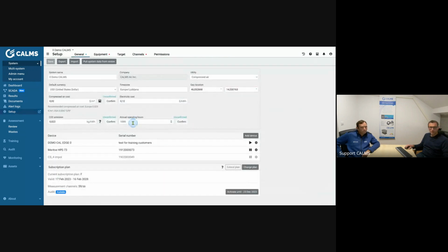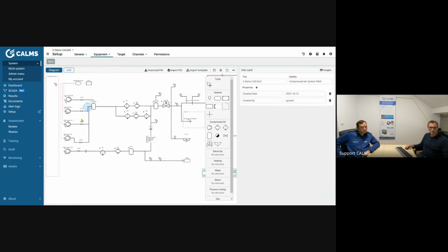So if I open this page, just for everyone to know, we have 4 compressors, and the new one, which is located on the other side of the compressor room, with a separate filter and separate dryer, and also you put a receiver here, even if it's a VSD compressor. The receiver was there before. And there is the connection pipe, which is 2-inch. No, it's 3-inch, sorry. With a 160 kilowatt compressor. It was 2-inch before, but we were experiencing some pressure drop, and they fixed the piping to 3-inch.